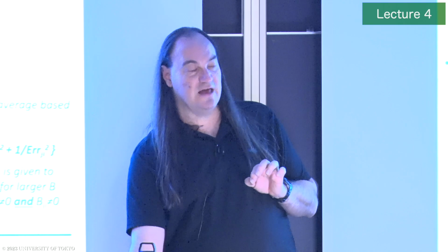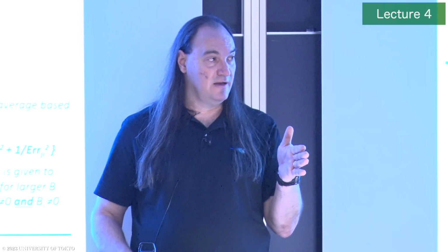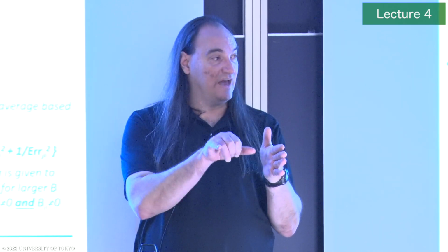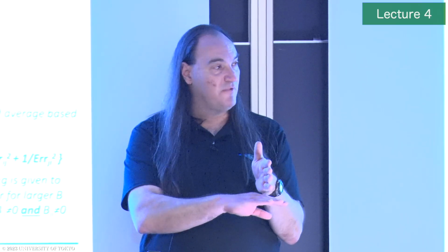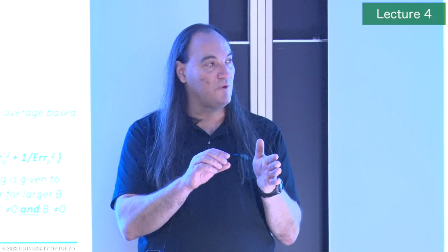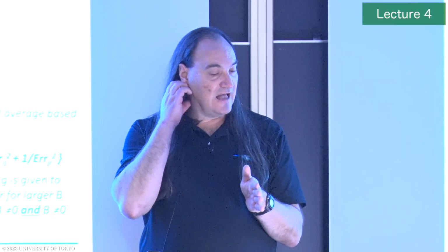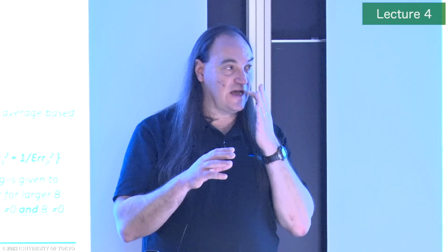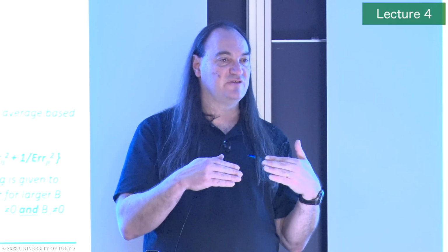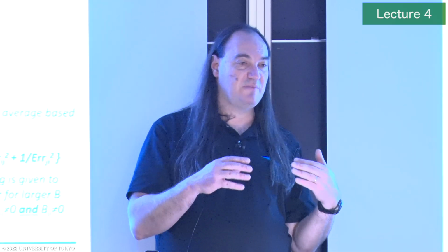What I'm going to do then is take each Bij multiplied by its error, sum all those up, divide it by the sum of all the Bijs, and that is what we call the weighted error. And you'll notice there's an update frequency or number of rays to fire before checking. That's usually about 5,000.